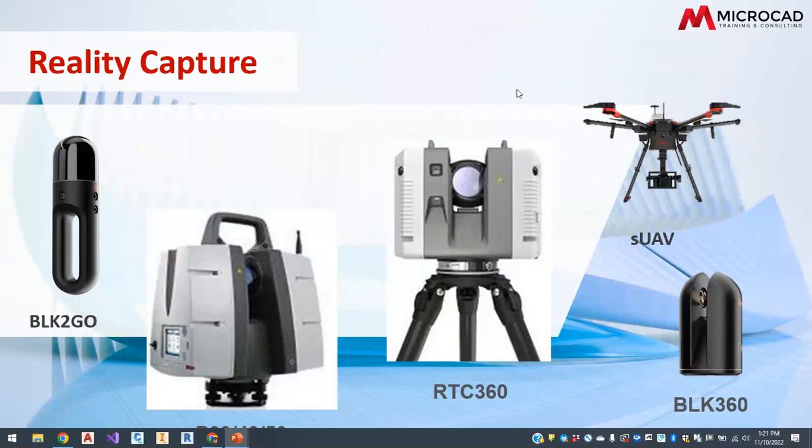So it's a bit more powerful, has more range, but again, as I mentioned, takes a little bit more time to collect that scan. The RTC 360, great for interior work and some exterior, but just a little bit less range on it than the P series. But it does have the benefit that it's very easy to set up and move from point to point because it tracks its location as you move it. Price difference wise, RTC 360s are about 3/4 the price of the P series, give or take, but you pay for that extra range should you need it.